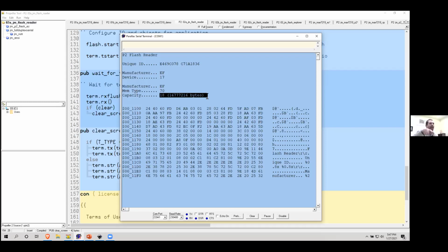But that inherently wear levels, right? Because you're traveling around in a big loop. And there's also some safety in that, because if the power were to go out at some point, you're only one delta bit away, you can figure out where you failed and then go from there. So there's some fault tolerance in that sort of system too. But you have to wear level, because if you kept your file allocation table in the same place and kept erasing and reprogramming, that's going to fail far earlier than the rest of the chip.